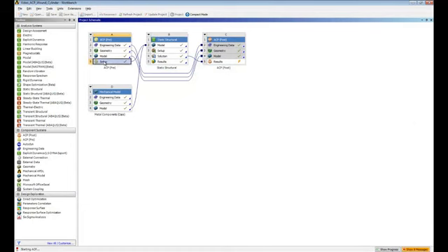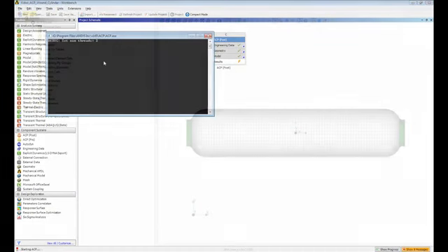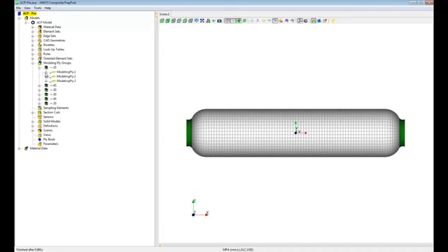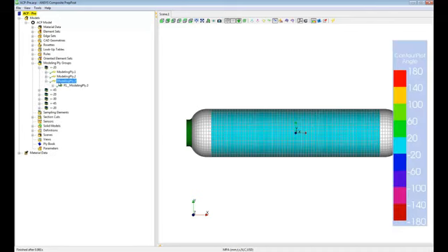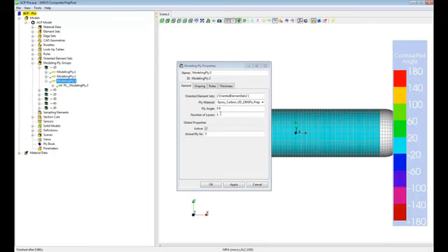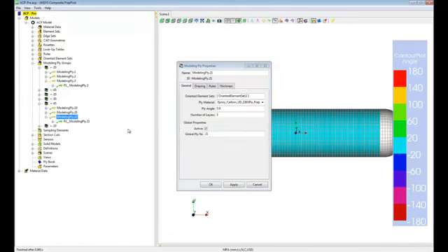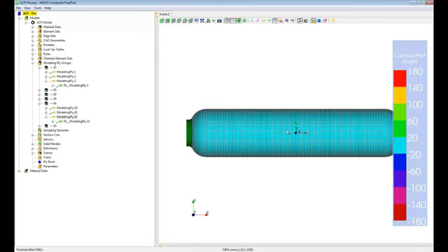The last thing we are going to look at is how to change the model. Let's say we want to put more plies because we have identified there is a potential failure. So we want to take a given ply group and increase the number of plies that corresponds to this existing group. So here we change the number of layers from 1 to 4. We are going also to change our central part. You remember the one we had localized, and add 4 layers as well here.